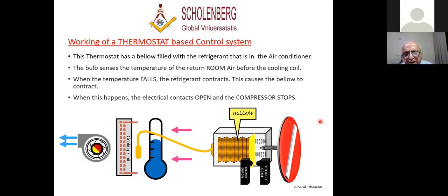Because if you're an air conditioning engineer and you have this application, in place of a thermostat there are other controls, like a TEV with an external equalizer. The TEV also has a bulb. And what happens if the bulb breaks? If this capillary gets punctured, what will happen?